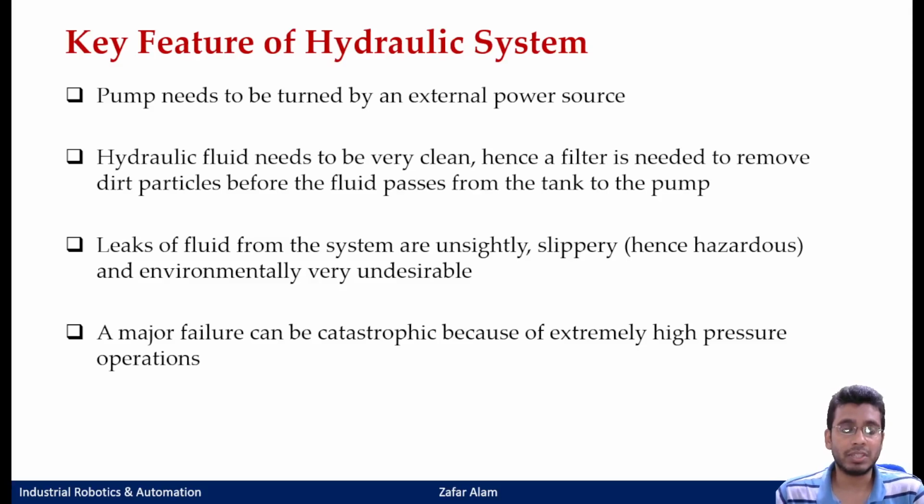Since it is an oil based system, there are some problems related to leakages, and in some cases it would prove to be a hazardous situation if there is a leak of pressurized oil. And because of the extremely high pressures that we work with in a hydraulic system, a major failure can be catastrophic.